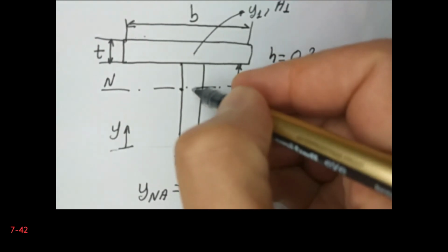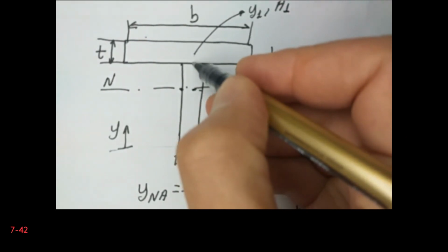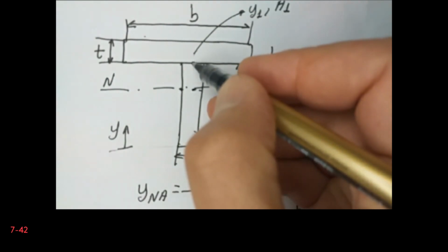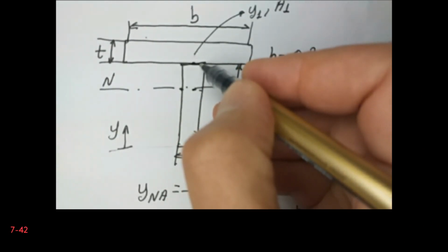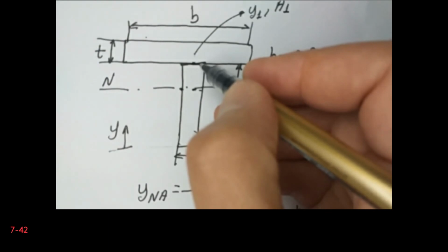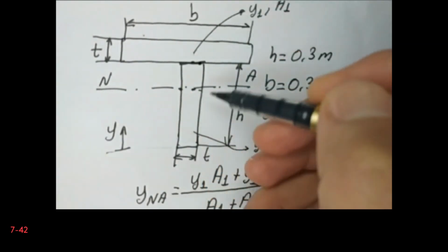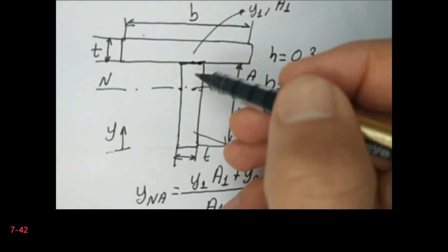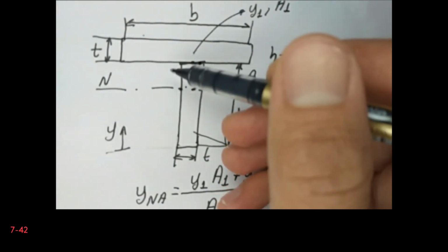Now, of course, this is the Q value for the neutral axis, and in fact we need to know the Q value of this particular location, because this is where we need to calculate the shear stress, because we don't know whether the wood will fail or the nails will fail. So we must find the shear force which will satisfy both conditions. Therefore we need to establish a relationship between the allowable force of the nail and the maximum shear stress. So we are given the maximum shear stress.